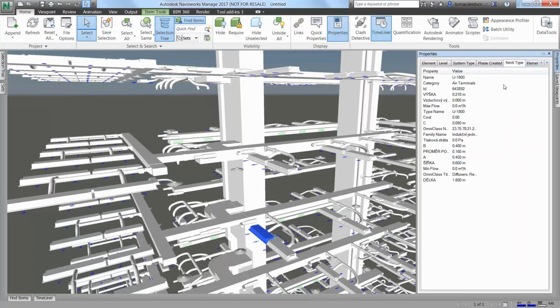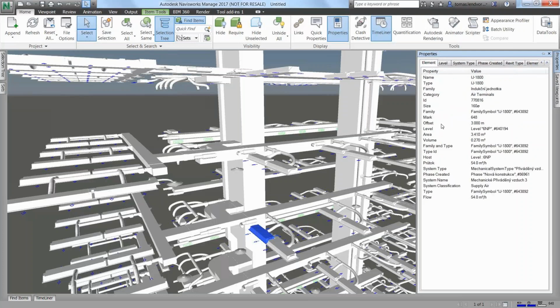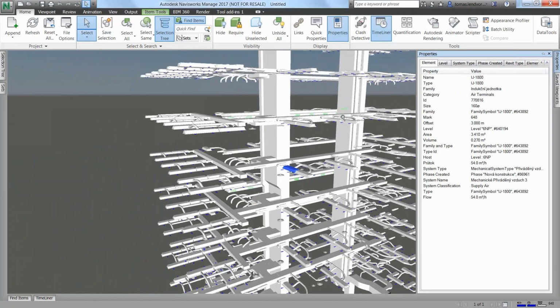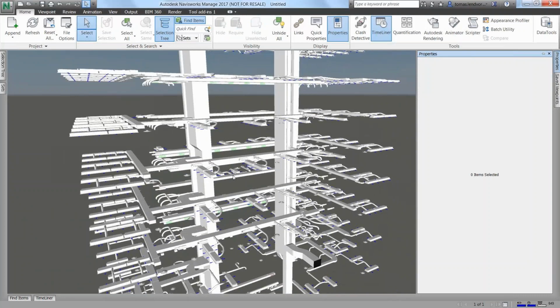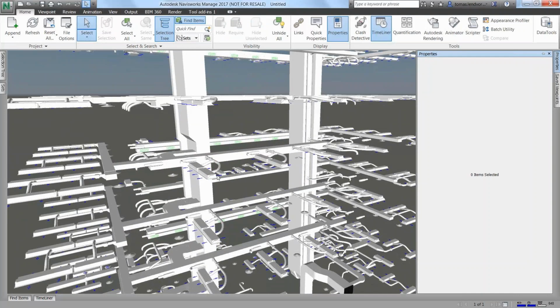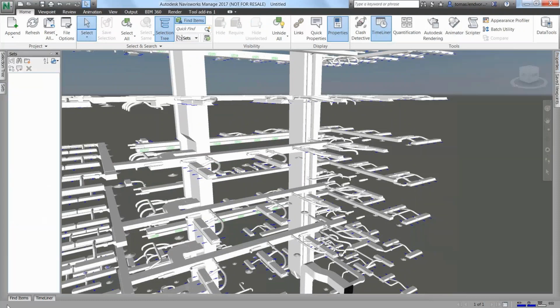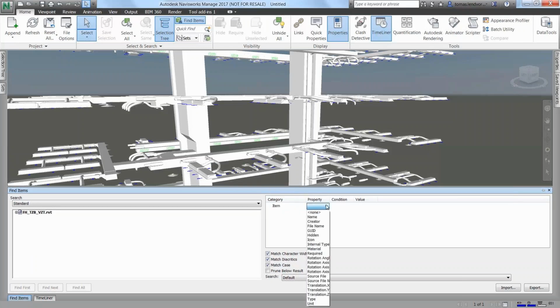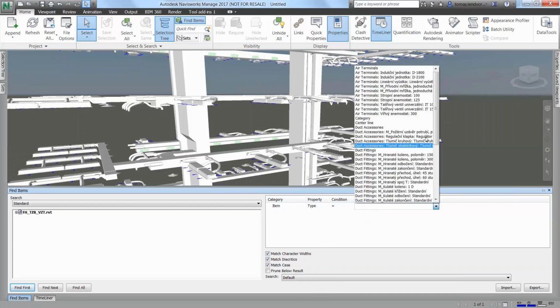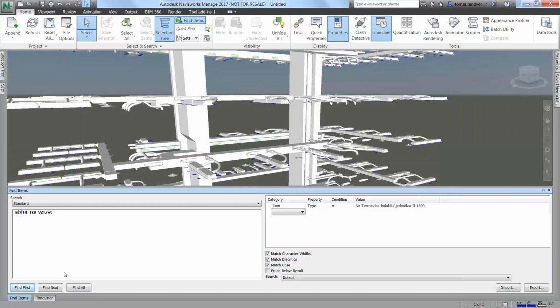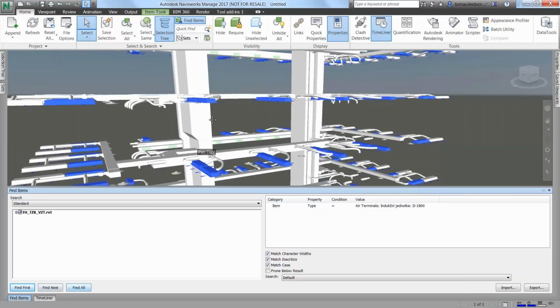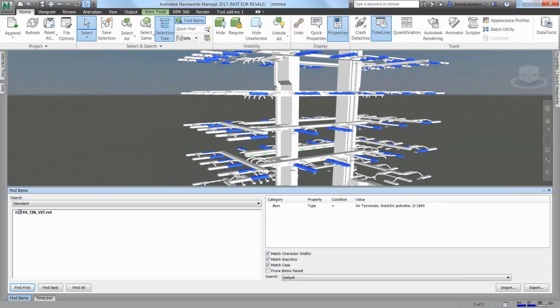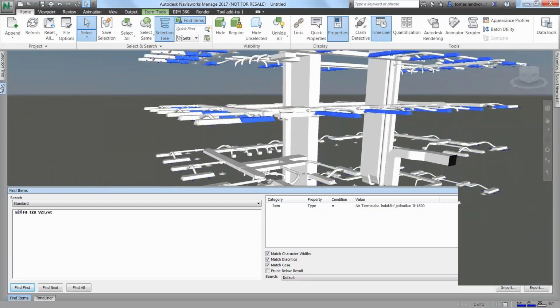And as a supervisor, I want just to review this information through Navisworks, because again, I am not a designer, I am not interested in learning Revit, but I need a tool to view all information which has been created. And Navisworks is very rich in functionality in terms of, for example, filtering information, because we have all information, all properties, and now I can search my model for all air terminals 1800, and the system will immediately pick all this information from my model.